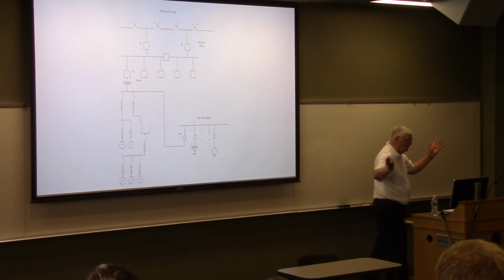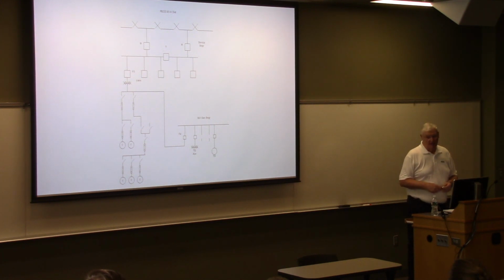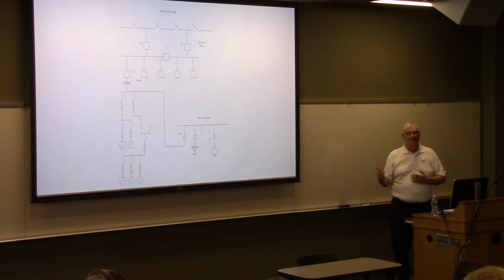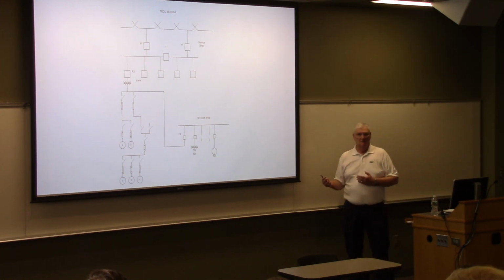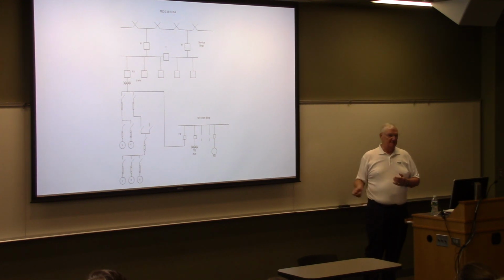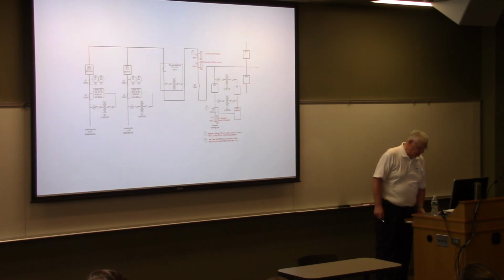It doesn't mean anything to you. What it means is that with a Y connection, it produced a lot of third harmonic current, like full load third harmonic current on the neutral that flowed into the system, and therefore we couldn't load the machine to anything more than 1,500 kilowatts. So we had to go back and revisit this transformer and the system in order to solve that problem.